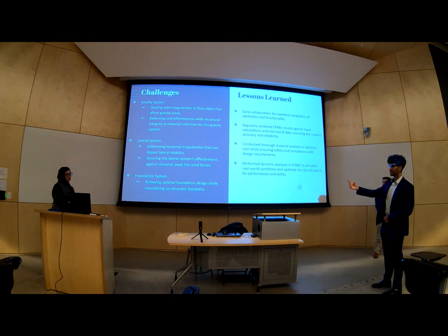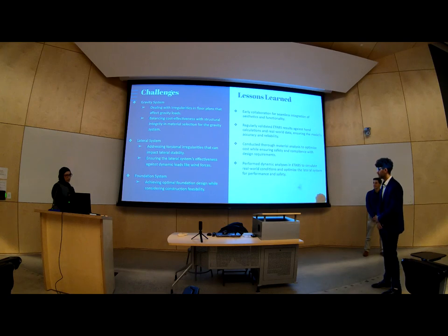For the lateral system, if you saw earlier, we had a bracing issue. Originally we were gonna keep changing from 9,000 PSI, and as you saw the different designs for the displacement, we decided to just put a bracing around the 25th floor, and that just cleared everything up. And then for the foundation, it was just a lot of confusion, but we got through it.